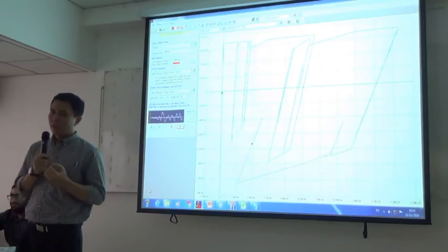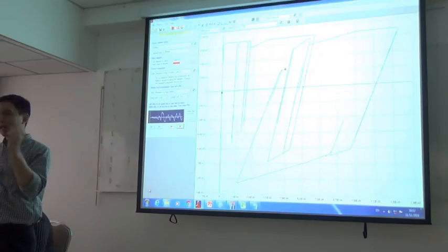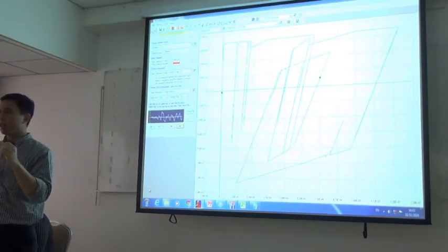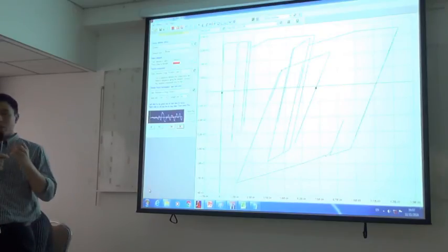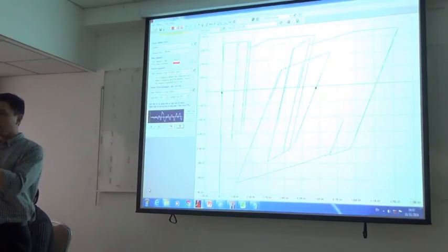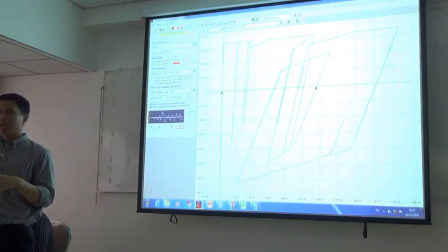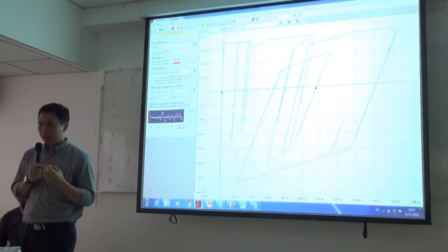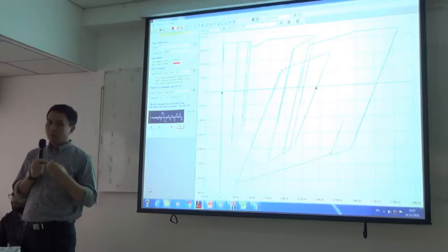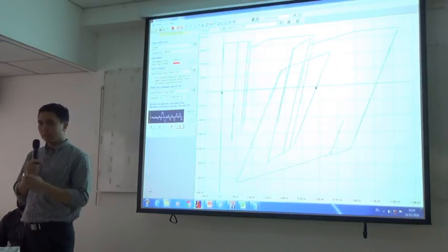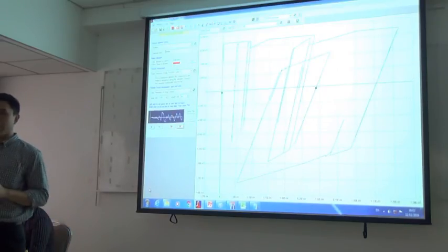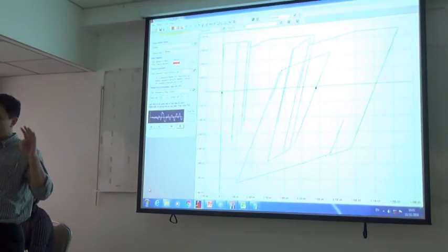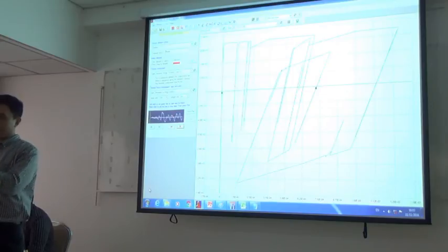Another thing is, in ETABS, when you draw a beam line element or shell element, the local axis is automatically assigned. But in Perform 3D, we have to assign the local axis separately. If we do not assign the local axis, we cannot run the model. And mass and weight we have to assign separately in the Perform 3D model. In ETABS, after you assign the loads, you can use those loads as mass source in the analysis. But in Perform 3D, we cannot use that. We have to assign the gravity loads separately and assign the mass separately.